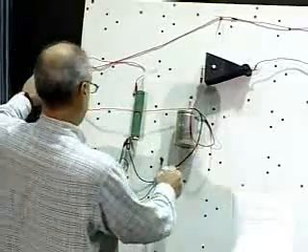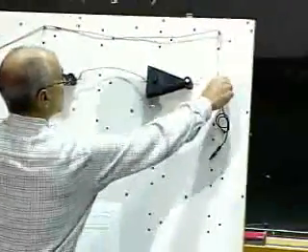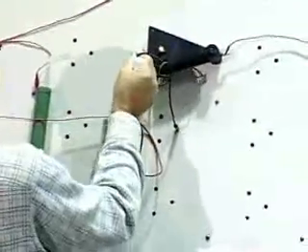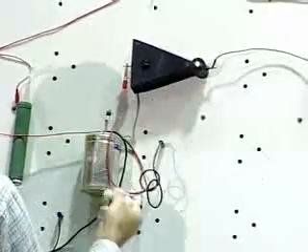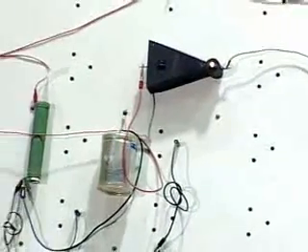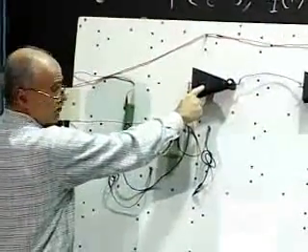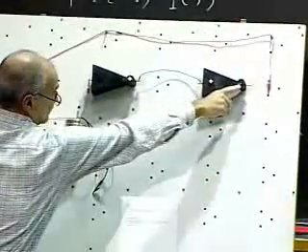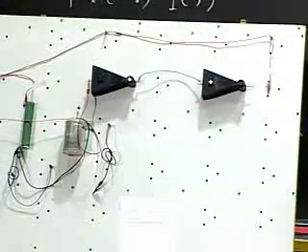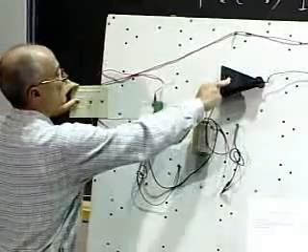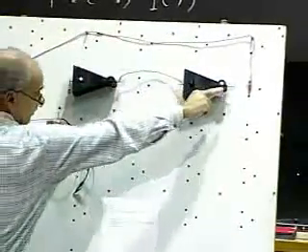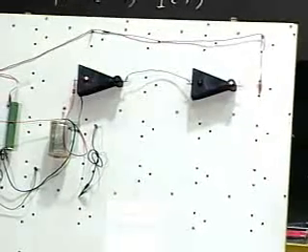In fact, let's see, maybe I can discharge the capacitor first. Okay, so here the capacitor is discharged. As you can see, the input is 0, the output is a 1, and then the output of this inverter here is a 1. I have 2 inverters in series. Now I'm going to charge the capacitor. Okay, so I charged it to 5 volts. This lit up. This is off, of course. That's an inverter. This is a valid 0, produce a valid 1.